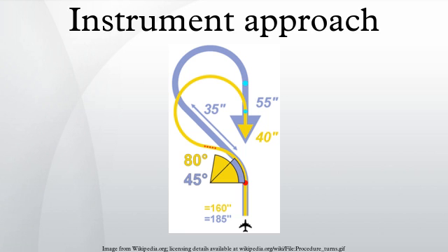Back course approach. A back course approach is a type of approach in which a pilot flies the localizer's course guidance on the opposite side from the original direction it was primarily designed to be flown. A front course approach is usually depicted by the right half of the localizer symbol being shaded on the approach plate. A back course approach is depicted by the left half of the symbol being shaded, as well as by a clear indication that the approach uses the localizer for the non-standard use.